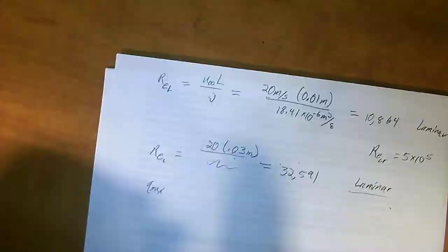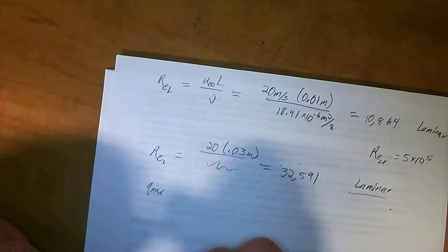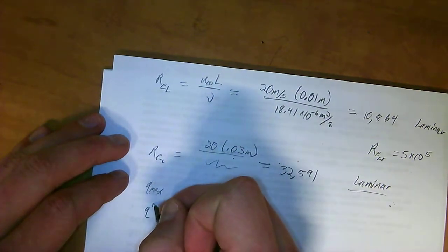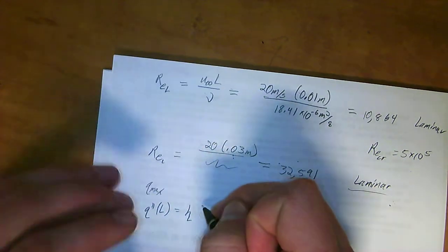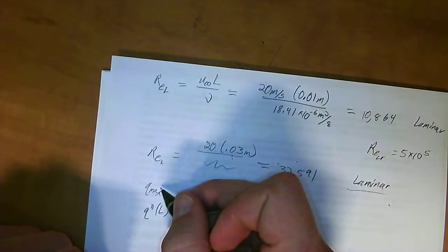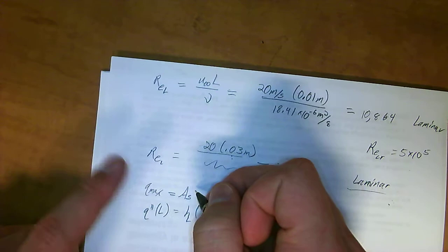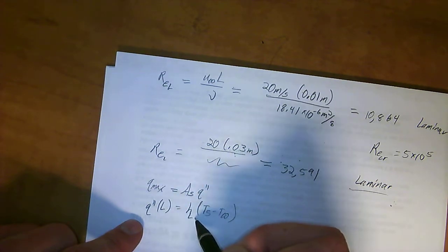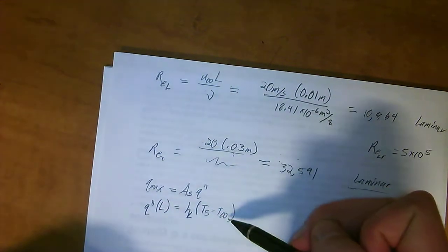So now what we need to figure out is finding the maximum Q max that can be transferred from the plate. In order to do that, I'm actually going to figure out what the heat flux is, because that's going to be a little easier to do as a general equation here. If you look at this as heat flux, Q double prime of the length, it's going to be equal to H, the heat transfer coefficient, times Ts minus T infinity, which means that Q max, the heat transfer rate, will equal A of the surface, the area of the surface, times Q double prime. That's just going to be an intermediary step here. So we're going to go ahead and try to find HL for this situation, because we have the T of the surface and we have the T of the air.